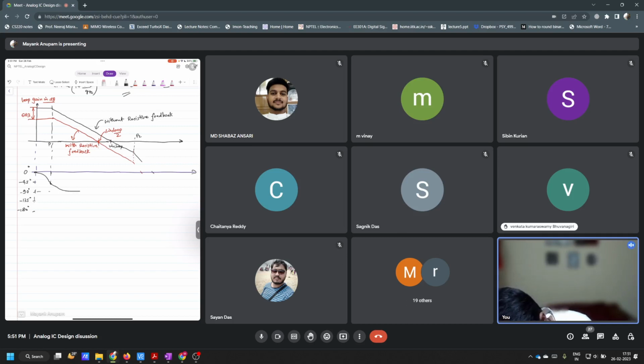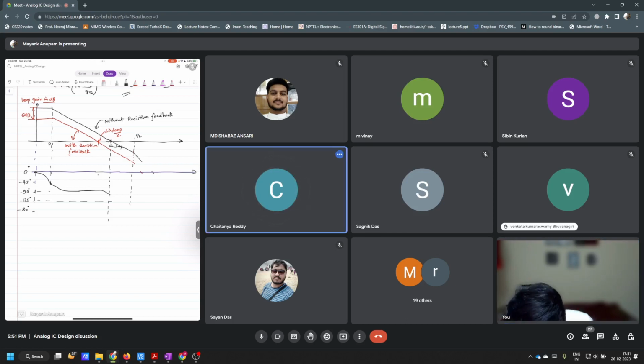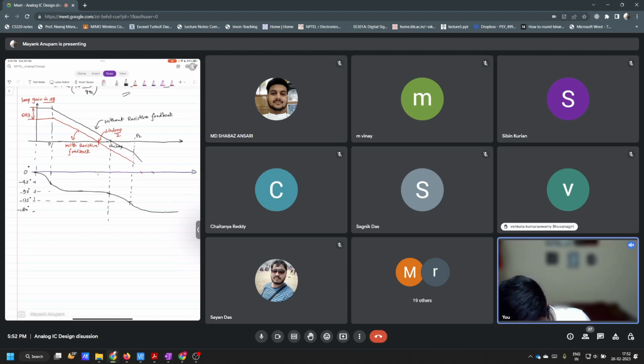So this is omega u loop, which is the critical point. This is also omega u loop, the earlier one. So around omega u loop, this will start. Let's say P2 and omega u loop do not differ by a factor of 10. It is less than 10. Then at omega u loop there will be some dip, right? And at exactly P2 it will reach minus 135, correct. And then after 10 times larger this will go to minus 180, right? Fine. So this is the plot earlier.